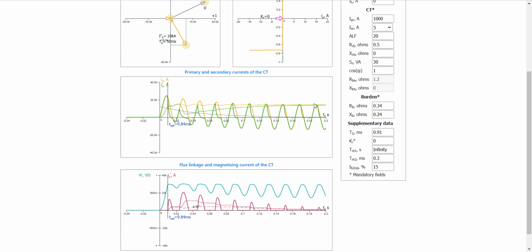The window of the Fourier filter with the length corresponding to a full period at the frequency of 50 Hz signifies that in the event of a sudden current increase, the protection device will know a new reliable value of the current only after 20 milliseconds. Let us therefore briefly imagine that we have such a protection device that works according to this principle. Its current measuring time, the so-called pickup time, is 20 milliseconds.